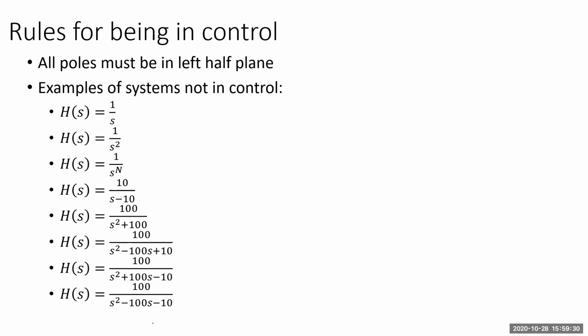Right, okay. So Nick, to be in control, a second order system would either be over, under, or critically damped. But you can have a first order system that's in control, but there's no over, under, critically damped, doesn't matter. You can have third, fourth, fifth, and sixth order systems that are in control or out of control, but they don't have the special name of over, under, critical. Higher order system, higher than second order, really you either have complex poles that cause oscillations if the real part is on the left hand side, right?